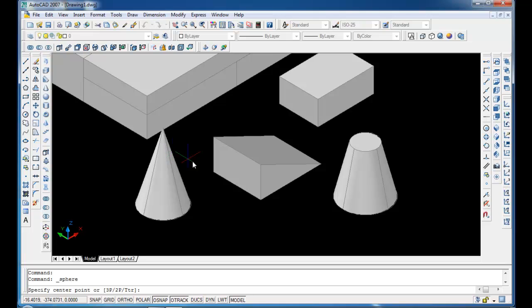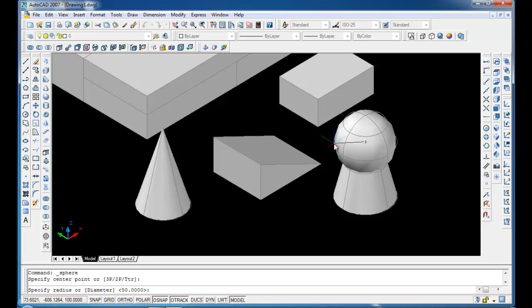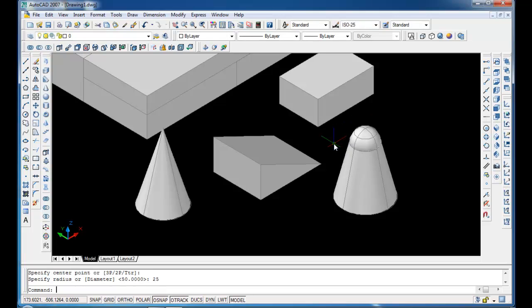Next you have sphere. Sphere means it is a solid ball. We are working with the solid model where it has got total material. Get the center point, give the radius, 25 radius. We are going to get the sphere. That is a complete solid. If you know the value, you have to click here. We are going to get the sphere.